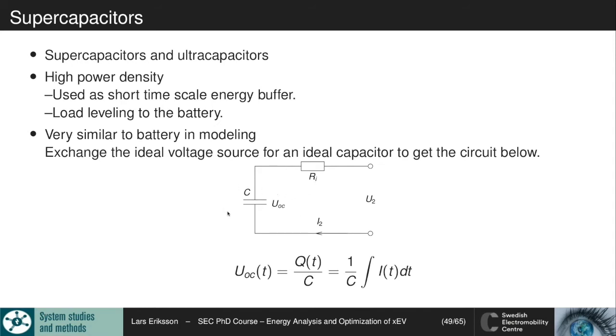So we have a storage here where we have a voltage that depends on the state of charge Q. So this is the connection between the voltage and the charge Q here, where we have the capacitance of the capacitor. And the Q here is the integration of the current like we had for the battery. So this is a core part in understanding the capacitor and using supercapacitors and ultracapacitors in the system.